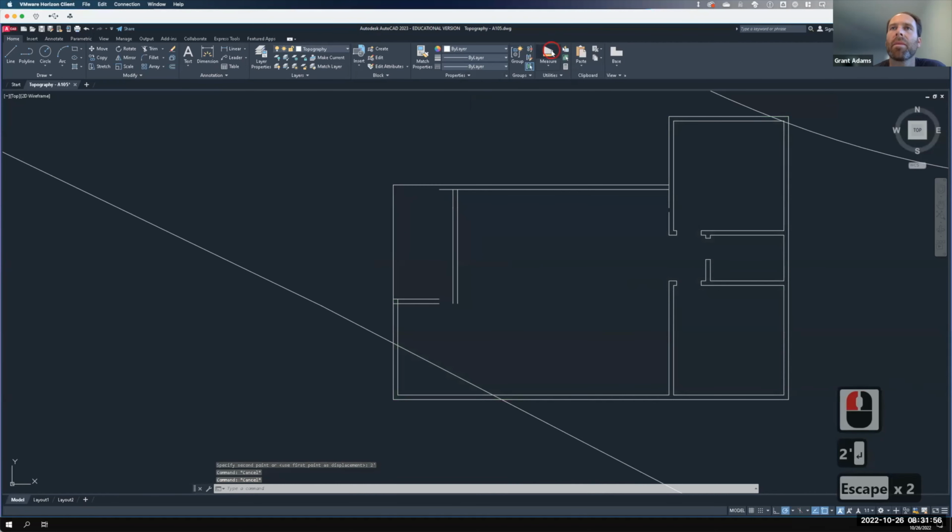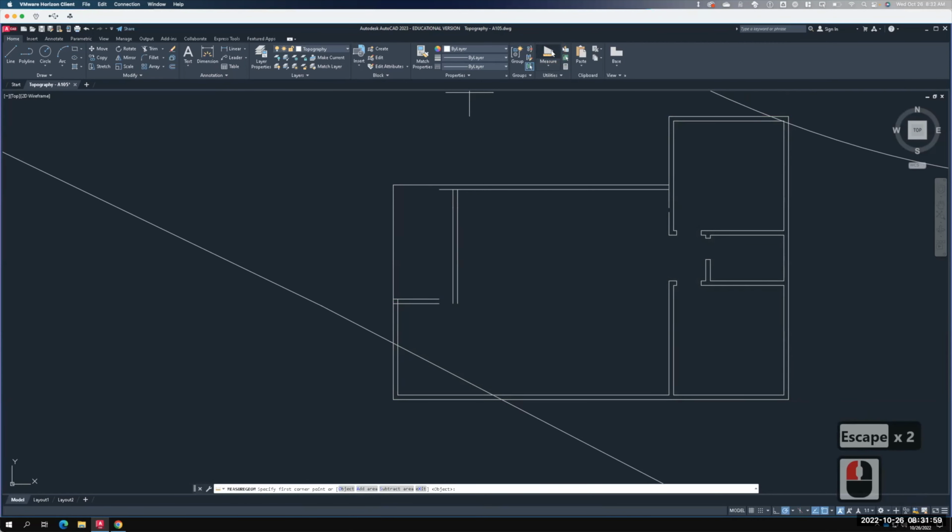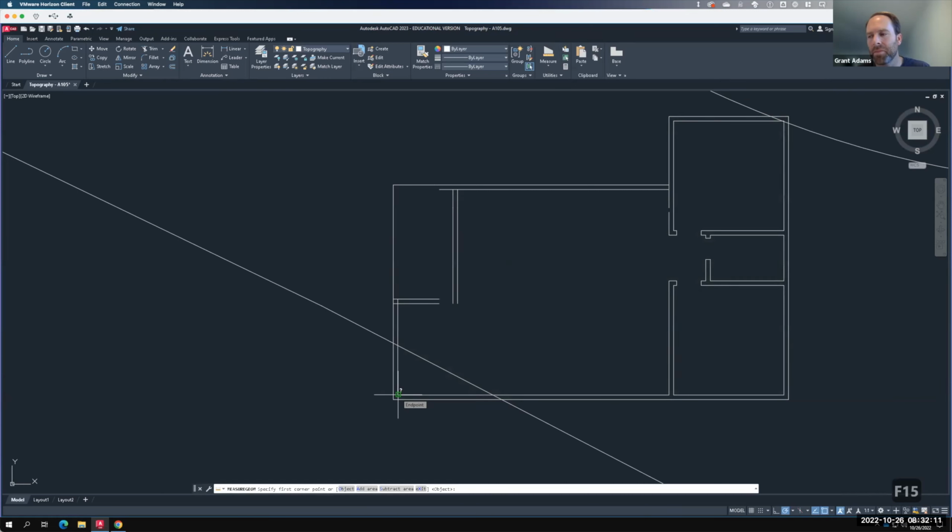Okay, so when I click on it, you can measure without the wall, so it will be less. Yeah, correct. So we can measure inside or outside. We can go off on tangents on these kinds of things. Technically speaking, it depends on what jurisdiction you're in, who's the authority as to how they count square feet. Sometimes it's interior square footage, where can you set your foot inside the building. Sometimes the perimeter of the building counts as square feet.